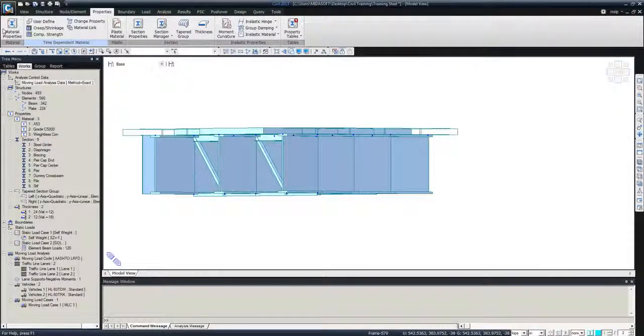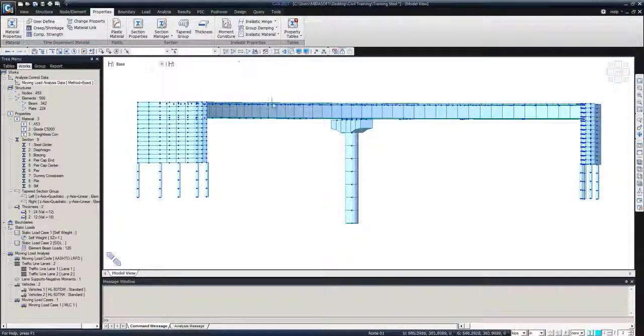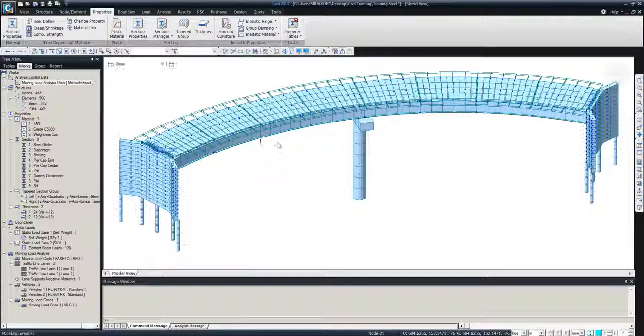Daniel asked why we entered the minimum number of traffic lanes as 0 and not 1. Yeah, that's a good question. We can just enter 1, but the option 0 is available there because, for example, you have 5 lanes and you want just two trucks to run through the entire bridge. So you have an option so that when you see the combinations, for example, one of the trucks is not applied on the structure. That's the reason it's already there.